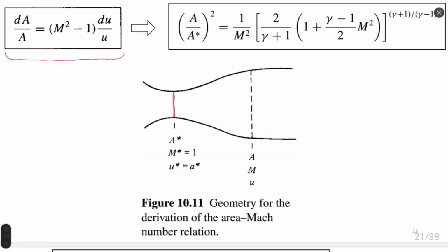And in this section, we always have specific flow conditions, right? We have Mach 1 inside the throat, and because of this, the speed of flow, or velocity of flow, is equal to the speed of sound, or vice versa. Okay, velocity is equal to speed of sound. This is why Mach is equal to 1. This specific cross section is called the characteristic cross section.